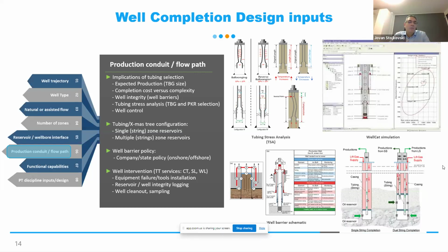If we really have a corrosive environment, we will not put in metallurgy which will be ruined in a very short period of time, because if this happens, then we need to count on a very complex workover, most likely a fishing job, and a lot of lost money to recover the well. Because if we initially pay several million to drill the well, and then we install a very cheap completion, then the final product and the well life will not be much, and then we will have more and more headache.